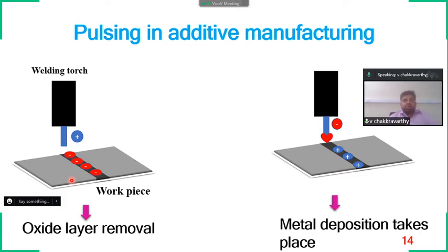The other most important thing we should note down is that powder based technologies require a specific environment. It should be completely done in a sealed environment where the oxygen is kept at less than 10 ppm, parts per million. To that extent we have to maintain it, and in case of electron beam based deposition, we have to maintain a vacuum, which is very costly if you are maintaining a vacuum chamber. We also have to purge the entire system with argon in case of laser based, I mean powder based, additive manufacturing techniques. That will increase the manufacturing cost a lot.